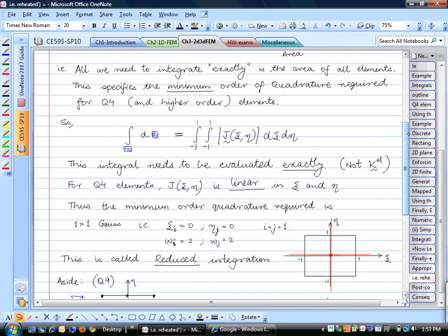Absolutely. So there are two types of error measures that people ordinarily use. The first type of error measure we've already talked about are called a priori measures, meaning you can estimate what is the order of convergence of your error. And in one dimension we talked about order h square. For linear elements, the displacement converges quadratically. The same thing happens in 2 and 3 dimensions. If your element is linear, your order of convergence in displacements will be quadratic, and your order of convergence in stresses is going to be linear, same order h to the power p.